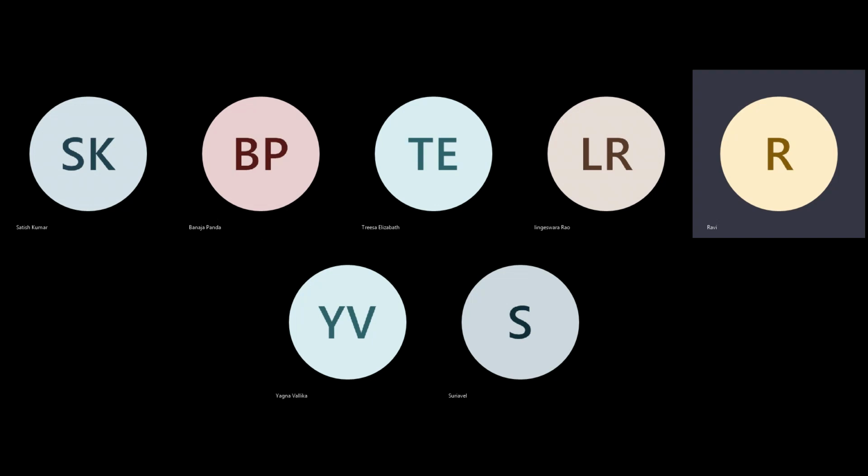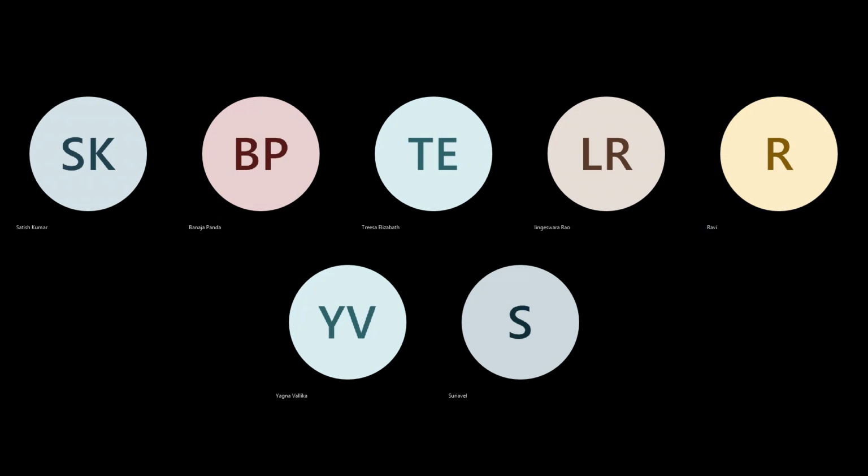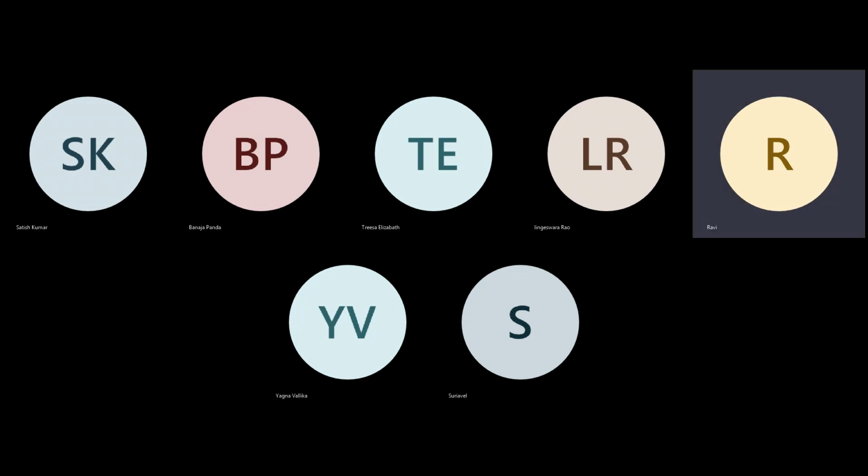Next it will check, okay, I have placed this, whether it is violating. The next check, after net length is fine, is whether my density is okay in this area. Say you have put density like 80%. By default, the tool has a maximum density of 95%.